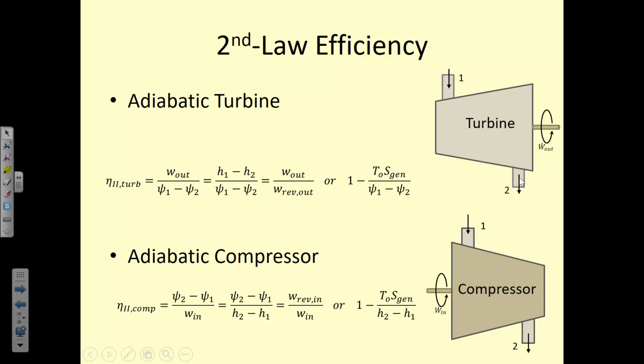And so that change in exergy, if we're assuming the turbine is adiabatic and it's reversible, would be equal to just the change in the exergy of the fluid stream. So we don't have any heat losses to worry about, no friction or anything like that. We can also rewrite the equation if we go through different versions of how to write the exergy destruction and work out and rearrange, which is shown in your text. I didn't do it for simplification here in this PowerPoint. You can also write it in terms of the entropy generated.